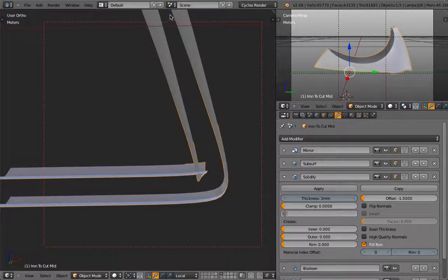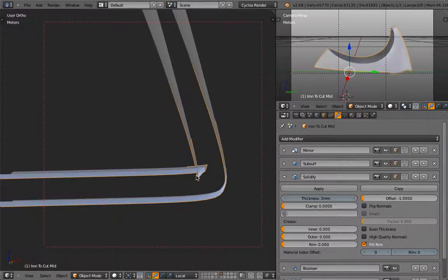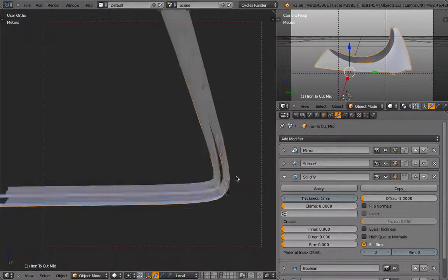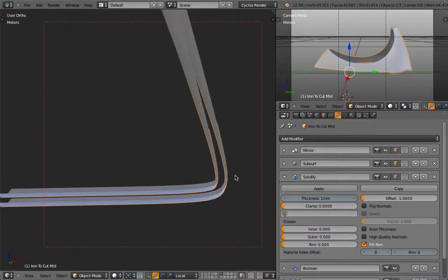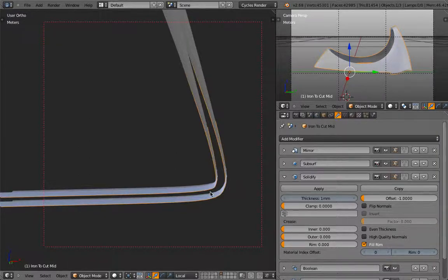However, the problem is those flat surfaces, they can be offset quite nicely, not a big deal. But here we have a concave surface or surface flow, and that results basically into this problem here. If maybe we only offset this by a millimeter, chances are high that it's not overlapping yet. See, for example, there. So that's just the radius is too small that when we offset it by 3, it's going to overlap.